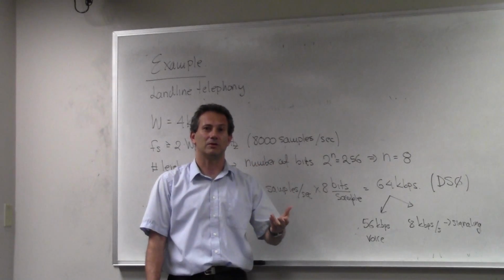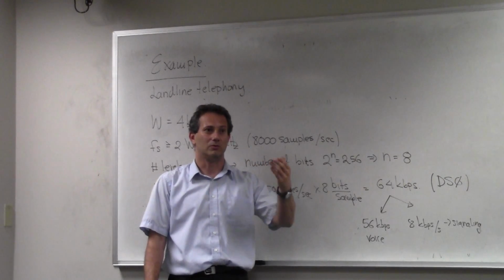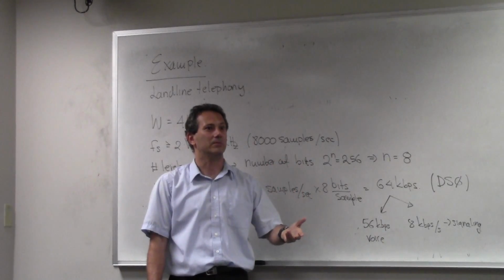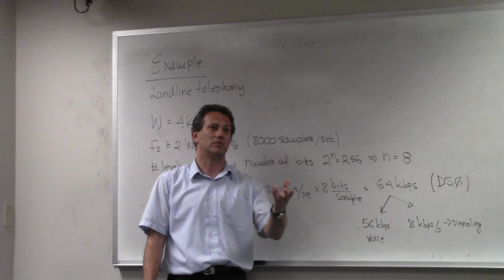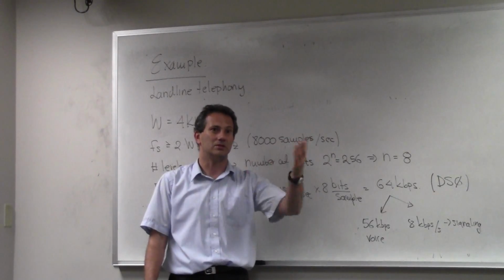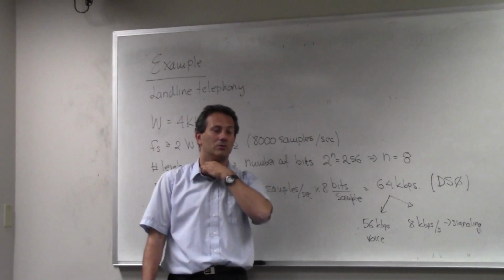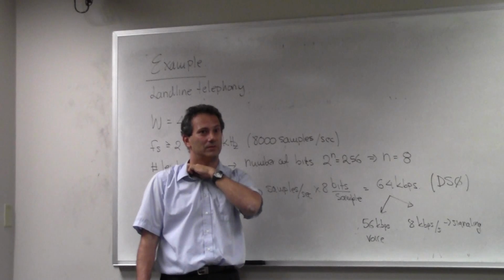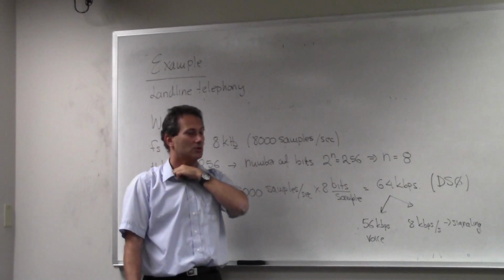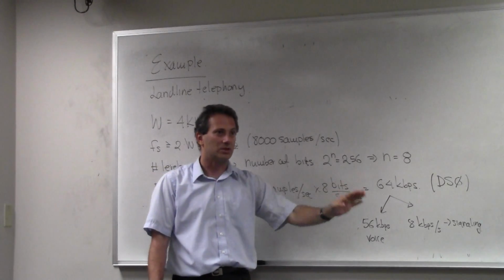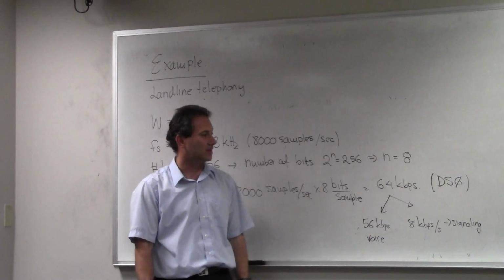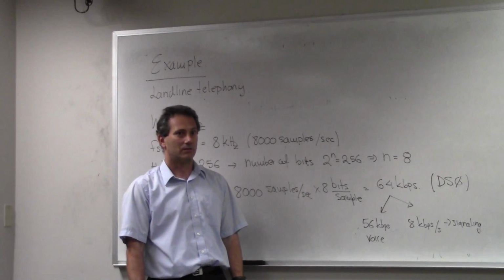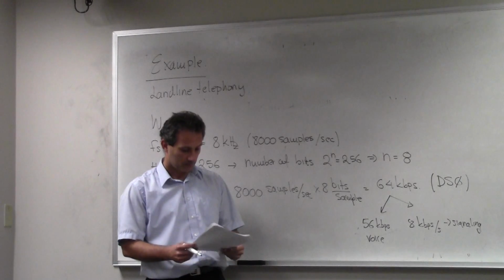But in data, you cannot afford to lose bits randomly because the system just decides to send some signal. That would trigger retransmission on TCP/IP, and your throughput would go even lower than 56 kilobits per second. So we just say, okay, here's your signaling. This is the most I can get from the dial-up. So that's it in North America.